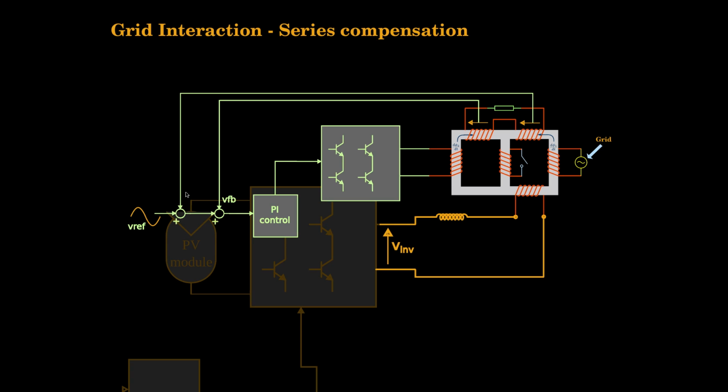So this minus this would be by how much the grid has to be repaired, or the difference by amount of which the grid has to be added in such a way that the voltage across the load will become pure sine wave. So this too, the subtraction of the pure sine and the distorted sine coming from the grid would be the difference makeup. That will become the reference here.